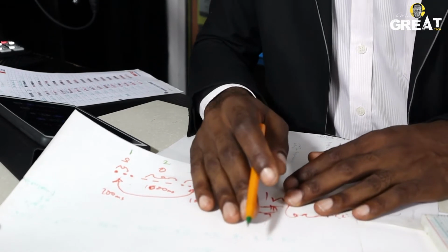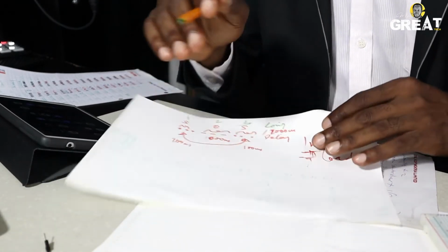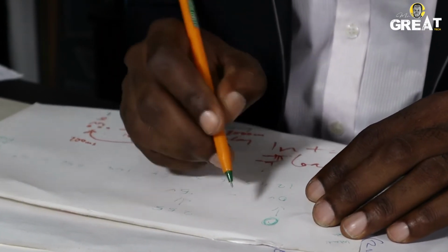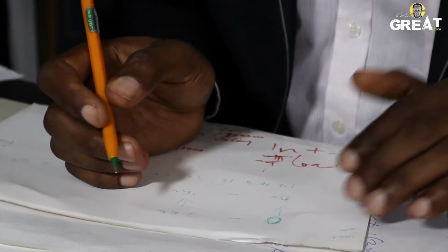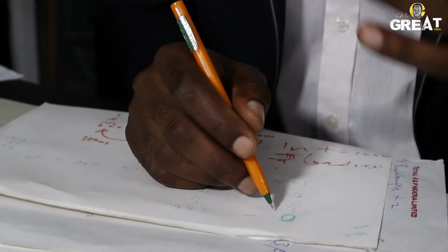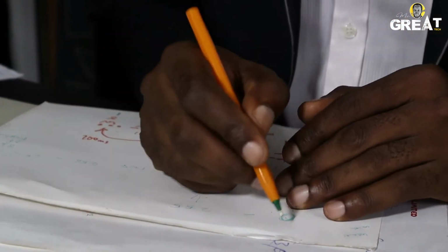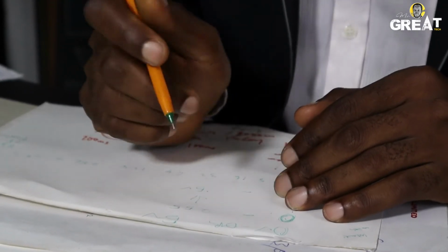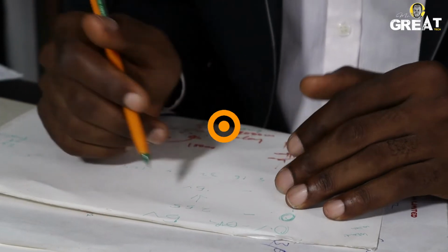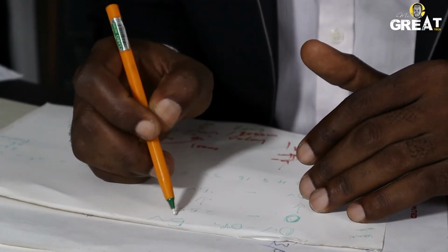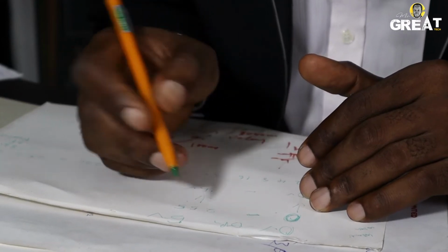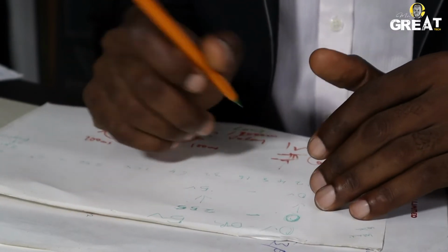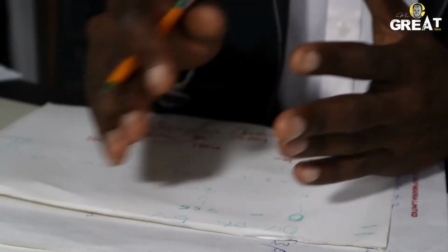In the analog write command, just like I told you before, you have 0 volts and you have 5 volts. Arduino gives either 0 or 5 volts. In the analog write command, the 5 volts is equal to 255. So that is the scale of resolution in Arduino.